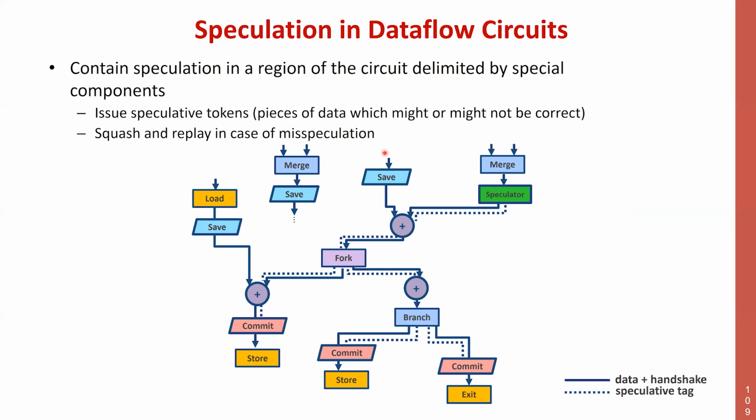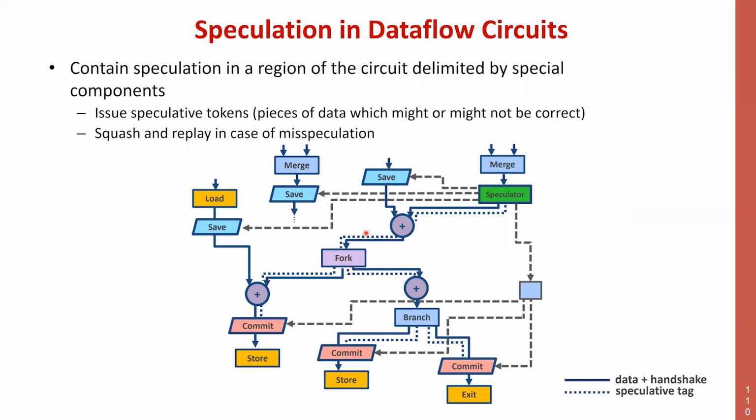Part of the register renaming is that you are keeping available the operands that were involved in the non-committed operations. In operations like this that are not committed, you keep it renamed and available until you are sure that you will not need it anymore. And this is exactly what you do here.